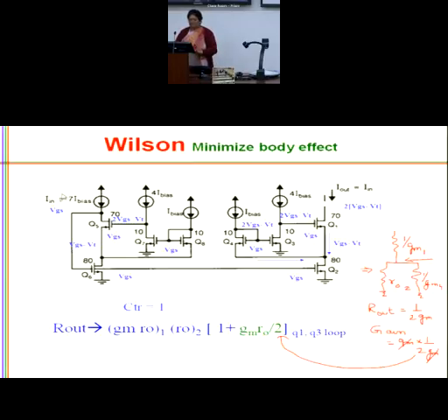It's not difficult to create a 7 times IREF, 4 times IREF. You can easily replicate by using a current mirror. You need to create only once, so that is not a trouble. But certainly, the more independent arms there are, the more will be the power consumption. So the more hardware you put in, the more complicated you make your circuitry, but the efficiency will be larger.